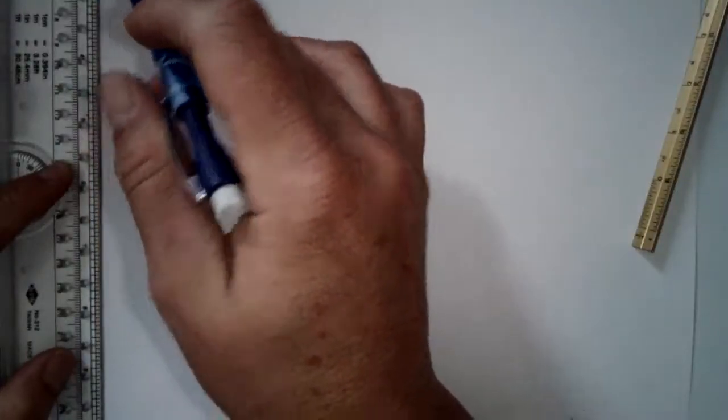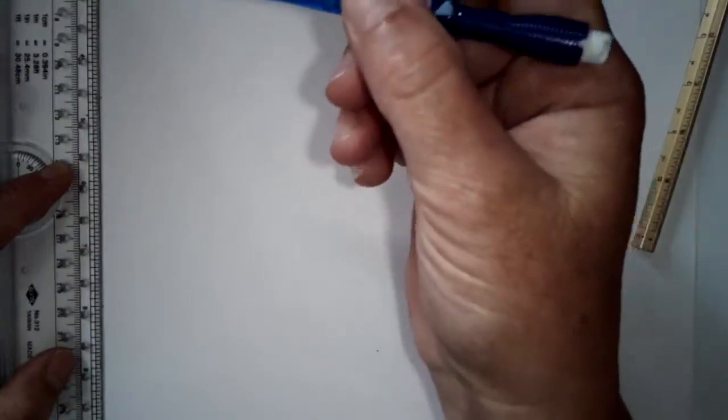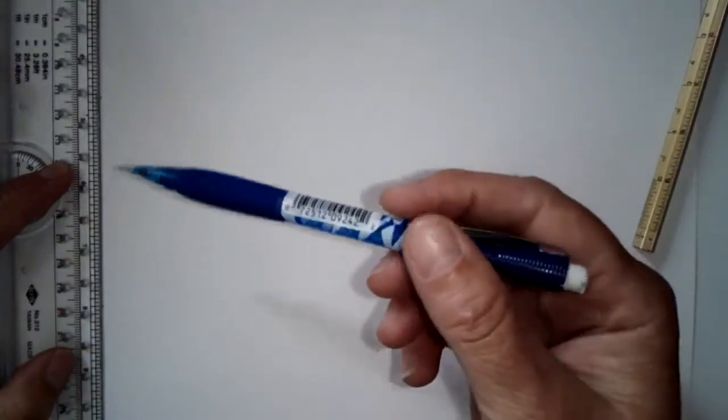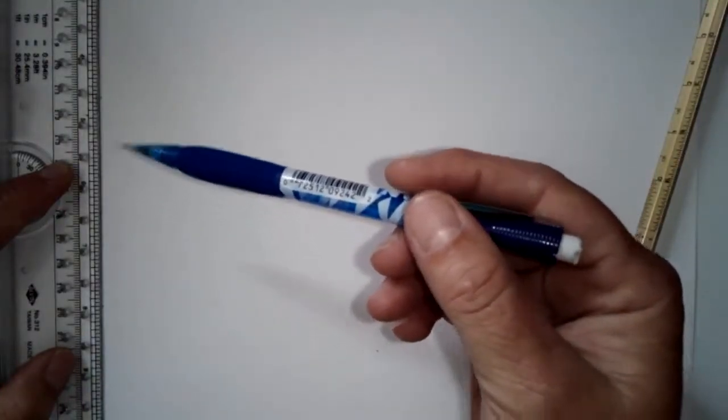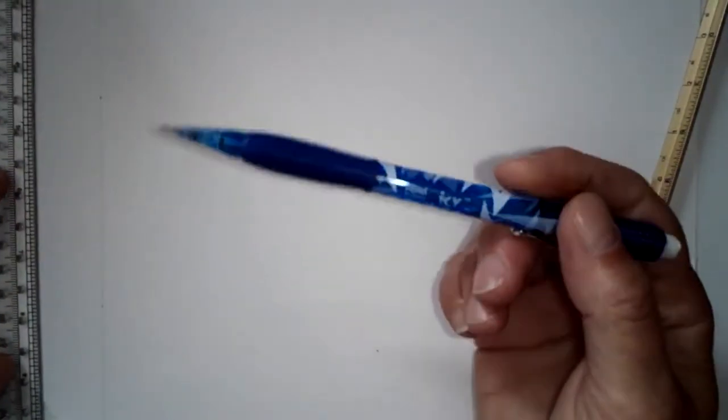So the first technique I'll show you to draw construction lines is to hold the pencil as lightly as possible. So I kind of hold it from the end like this and drag it across the paper, because that's what ensures that the line weight itself is going to be as light as possible. So you can see, we can barely see it, but we can see it enough to give us some guidance when we're drawing out the rest of the drawing.